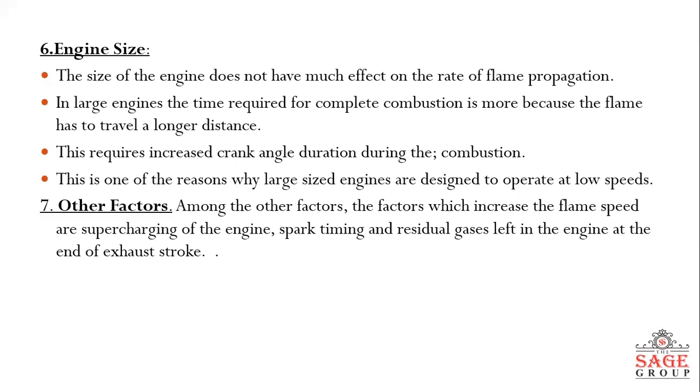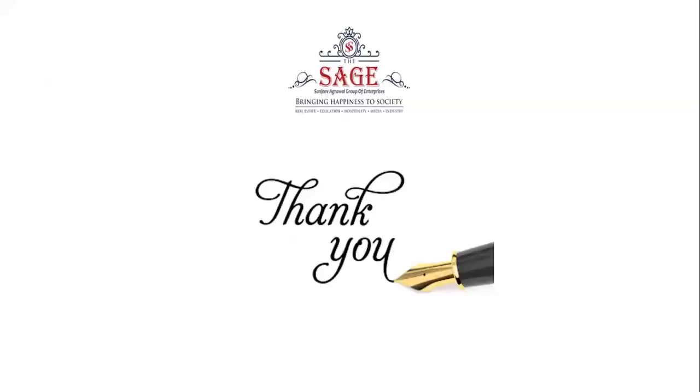The amount of residual gases left also affects the flame propagation. If a large amount is present there, then in case of exhaust stroke, the unburnt fuel particles may be there. So for this, what we do, we generally supply a slightly lean mixture in case of SI engine. So these were the factors which are affecting the flame propagation in case of SI engine.